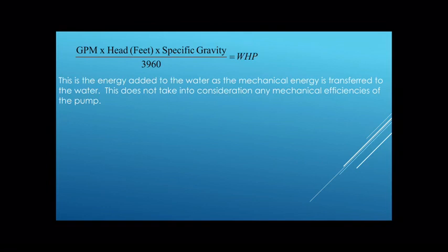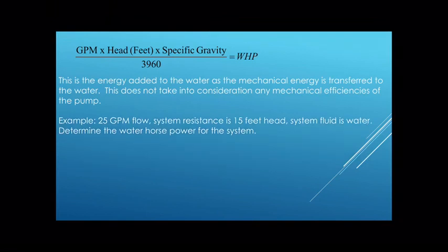So in this case, I described to you a little bit on how we do this. The energy that I'm adding to this water is mechanical energy. We're transferring it to the water. So it does not take into consideration the mechanical efficiencies or inefficiencies of the pump. All pumps are going to have some inefficiencies, and I would say they're quite inefficient in many cases.